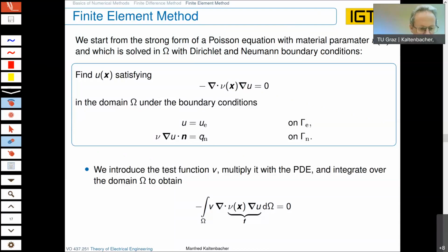Okay, so last time, as you know, we already have started with the finite element method. And I just want to summarize. So what we currently consider is this partial differential equation, which is a model for electrostatics, even for magnetostatics, when we can describe the magnetic field by a scalar potential U. Otherwise, U would be the electric scalar potential. The thermal field in a static case, U would be the temperature T. A potential flow, U would be psi, the scalar flow potential.